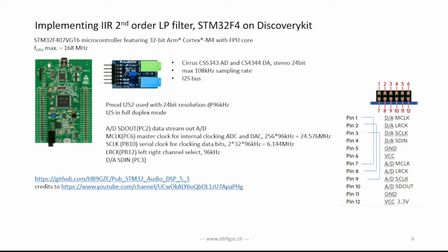The master clock is clocking the ADCs and the DAC, and typically that's 128 or 256 times the sampling frequency. In my case, that's 24.6 megahertz. So you have to be sure that you get 24.6 megahertz out of your GPIOs here. You have to be able to drive them, and then probably don't have too long wires. That's already a pretty nice transmitter.